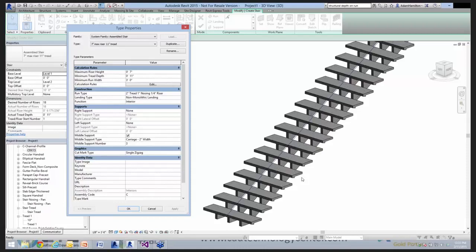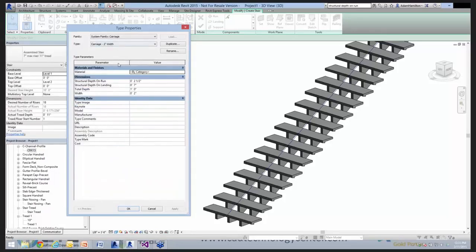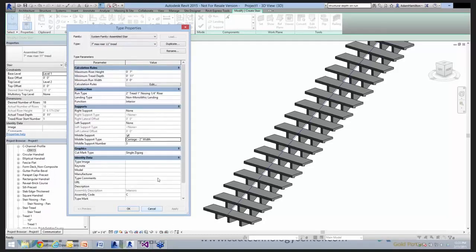And again, that's usually where some people will start to come back and modify or turn off the supports and create their own custom. So we have the ability to throw in these middle supports, and with that middle support, again, it's type-based as well. So being able to create your own custom type for that specific one is very useful. That way, you can have a different support style for each one of these supports: the left, the right, or the center.